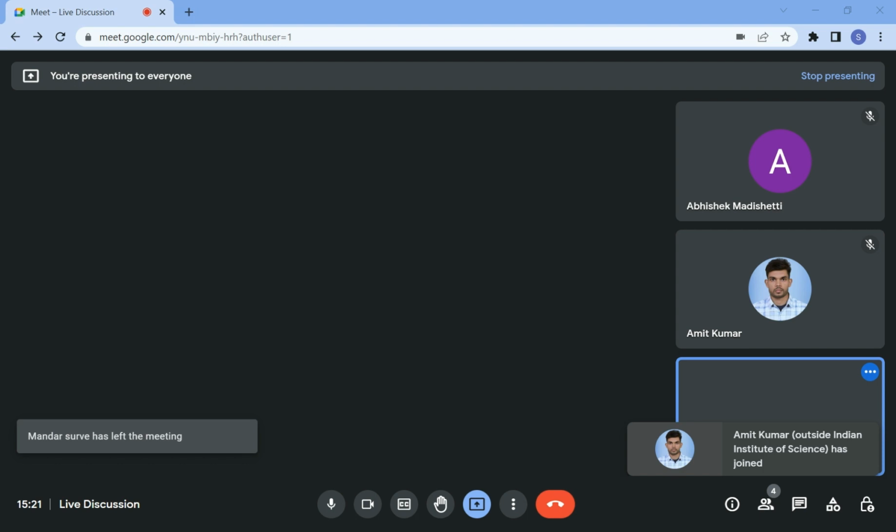So 10 mm above HP. So the distance with HP is seen in the vertical plane here. So this is my vertical plane. So I've marked A here, and 15 mm in front of VP. So if this is my VP, 15 mm in front of VP, the distance will be seen in the horizontal plane. So I will mark a point A here. So this is the projection of A dash.